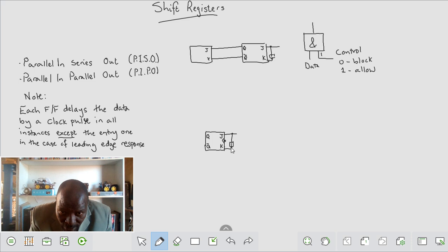The inverter is actually pointing at K. All right, the little zero is not on top there, it's actually at K. Our input is on J. All right, so what you then do is, if I'm going to read in a 1 directly or a 0 there, I need to be setting or resetting. Okay, so if I'm going to want a 1, I'm going to want to set this. If I'm going to want a 0, I'm going to want to reset.